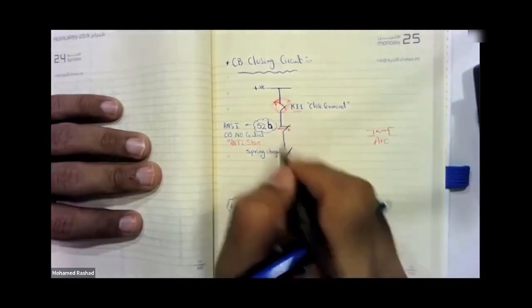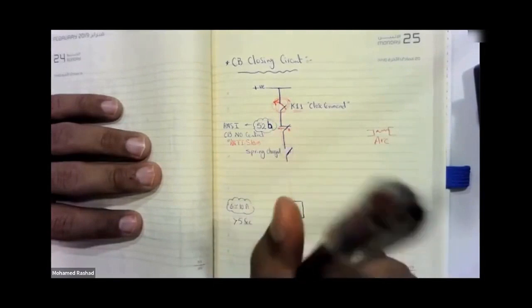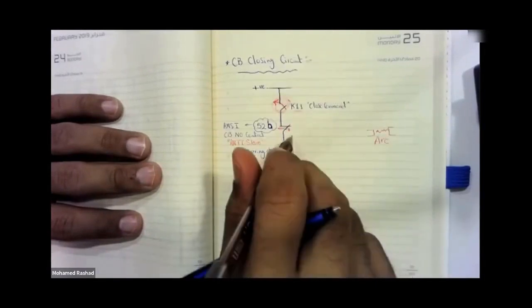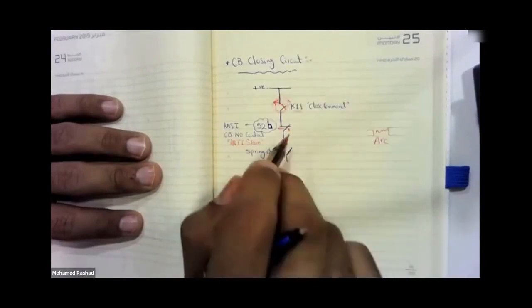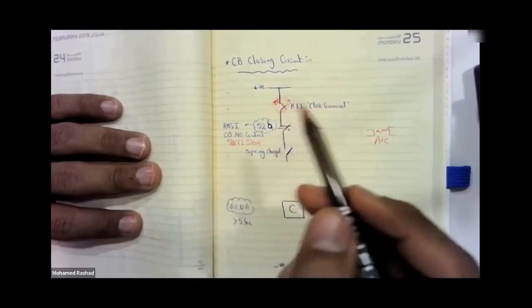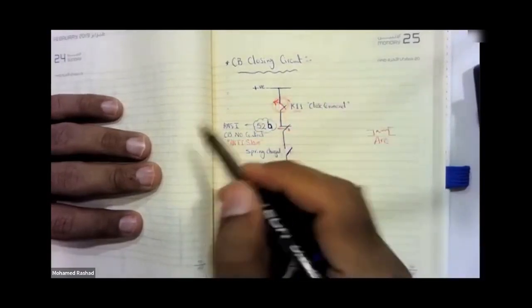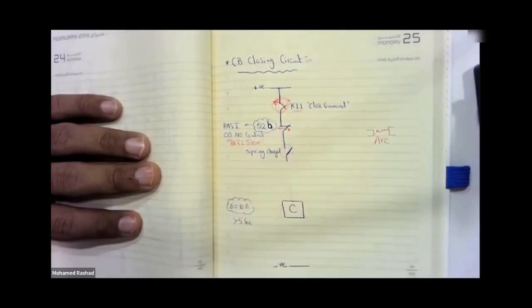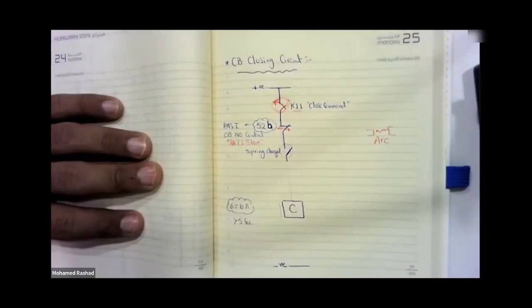The second issue is that this process repeats every 10 seconds, meaning every minute you will have 12 operations, 6 closes and 6 opens. So if the operator responsible for this station takes half an hour or an hour to reach the station or to address the problem, imagine an hour. That means you have 60 times 12, which equals 720 operations happening where? In the circuit breaker.